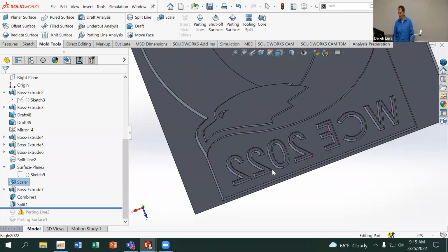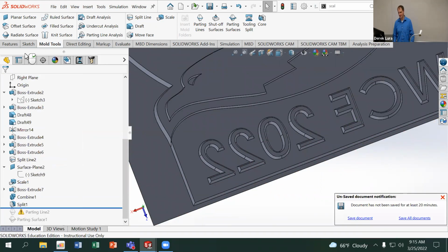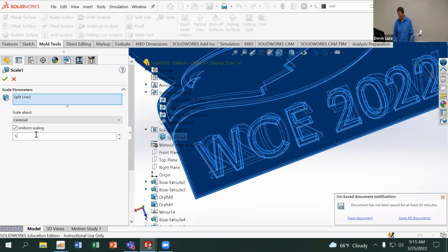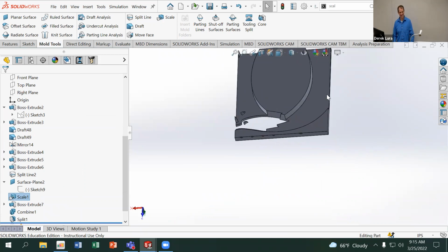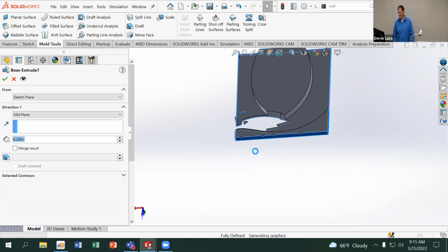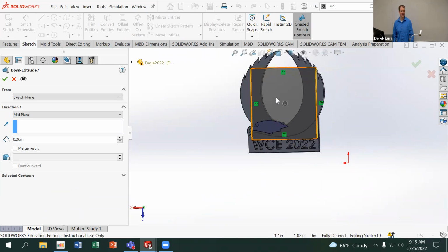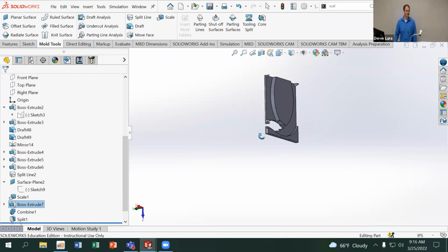You see my margins at the bottom here are getting a little too small. If I go too big, then obviously that's going to be a problem. So if I do, let's say, 1.5, now I have issues. But if I had set my features here to offset based off the size of the part, then it would automatically update and I wouldn't have those issues, right? If you're milling these things out, that's not always going to work because you're going to start with stock of a certain size. But if you're 3D printing it and then using that for a low temperature molding or something like that, then it's not going to matter, right?